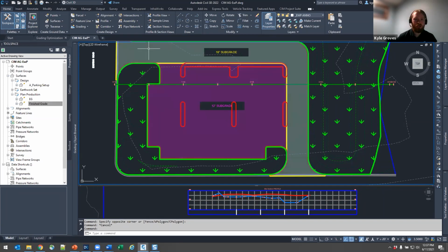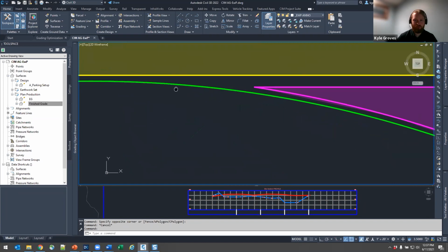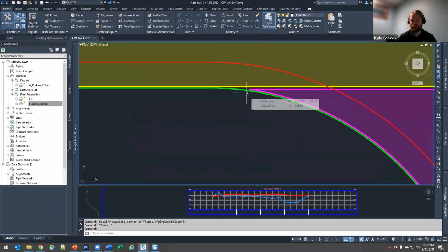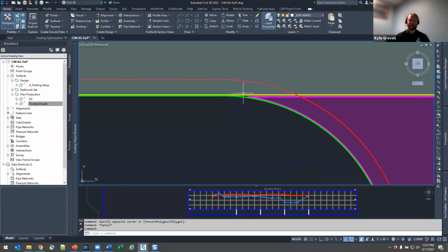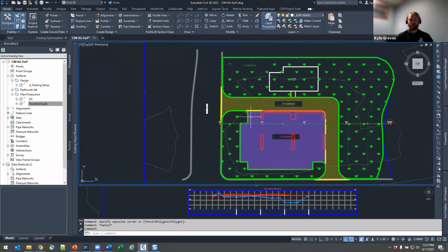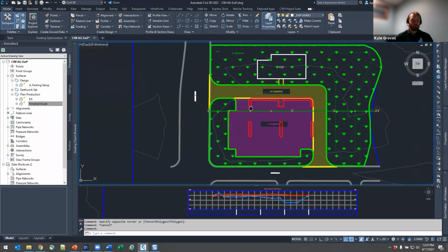of our lot. One really important thing here, these polylines are all offset just a little bit, maybe a 1/10 of a foot or a 100th of a foot. Because of the way that Civil 3D and most of its other competing civil engineering design software function, it cannot handle multiple elevations. It cannot handle multiple Z values at the same XY coordinate. So having those done manually is great.